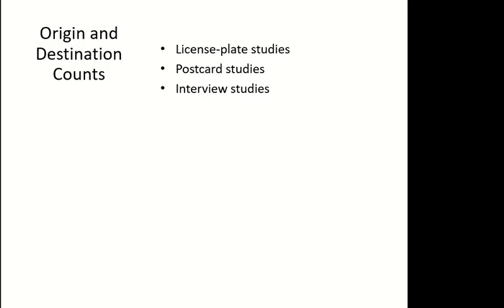And then you have the interview studies. Interview studies are still done in the same old way, but interview studies are more detailed. So they have more questions than postcard, and that's why they are usually done in the form of home-based surveys. So you go to the house. They are usually done by government organizations, and they conduct these types of studies annually. Not for origin destination purpose, but origin destination is made a part of this type of survey.